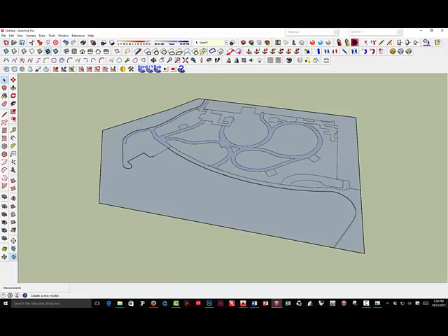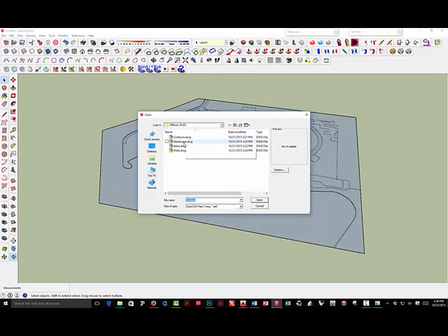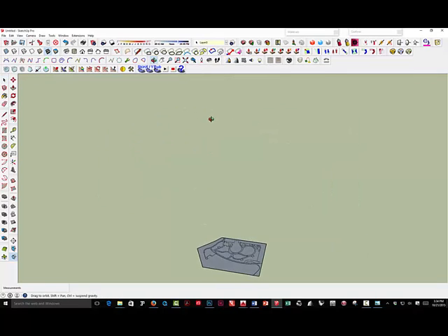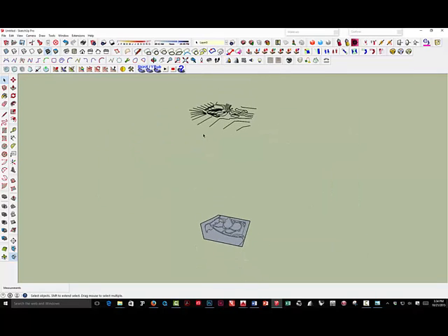Okay, so let's bring in the terrain now. Import that. Contours, don't have to check options. Now these, if I go extents, you can see the topo is up there where it belongs. And what I'm going to do now is create a terrain model out of this. Now it's kind of grouped inside here, so I'm going to open that up, select this. I'm actually going to cut that, close the group, paste in place. So it's in the same location, but it's not part of this group.